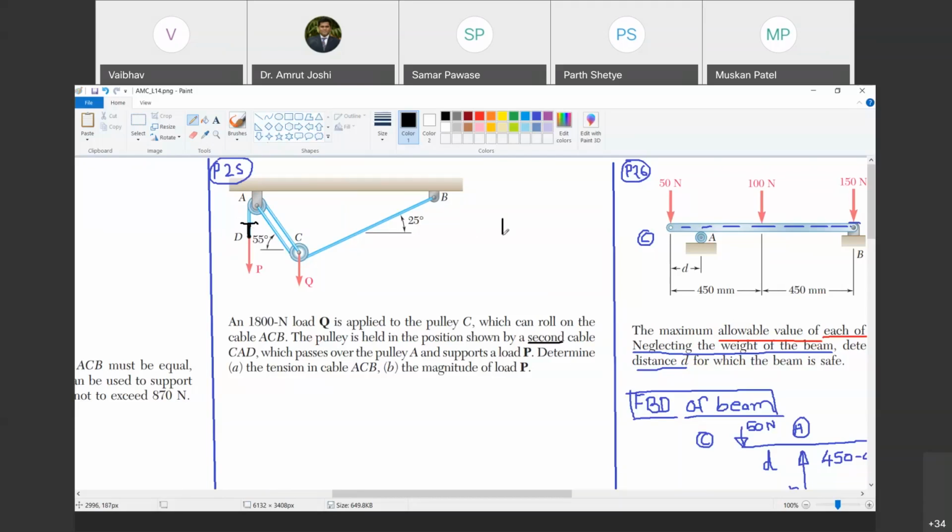So how will the free body diagram of this portion be drawn? This is the portion, this is a small portion of string AD. What is the force on it? P. Do you agree with me? Yes. And the remaining portion of string AD must be applying some tensile force T, which I am going to call TAD, tension in string AD. Are you with me? Yes.